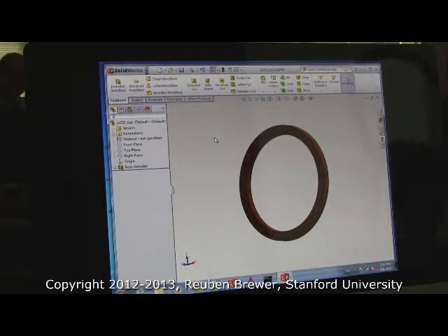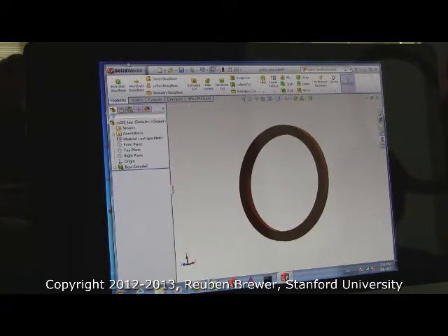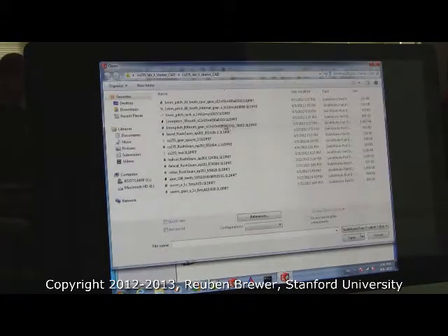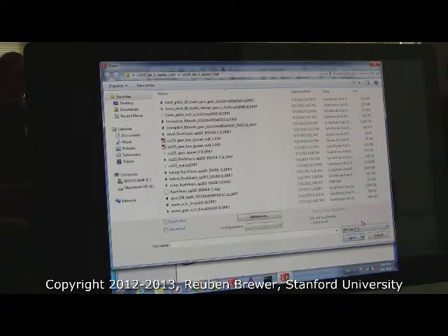Congratulations. So, now we're going to do the next part, which is significantly harder. Everybody, this one we're going to modify from CAD. So do File, Open, navigate to your folder, and now see right here I have like 30 different file types. Anytime you can't find a file, but you know what's in the folder, hit All Files. Okay? Now I want you to open the rush gears blah blah blah.step. It's the only one that's got a blank icon. And hit open.